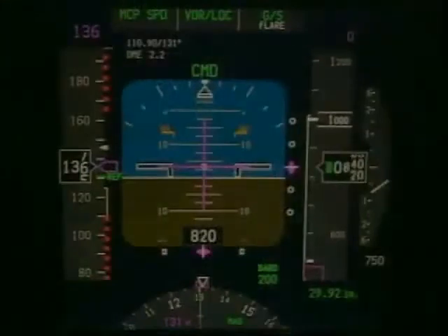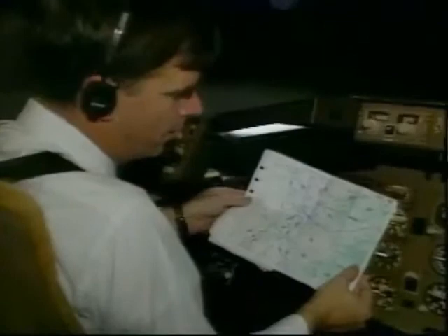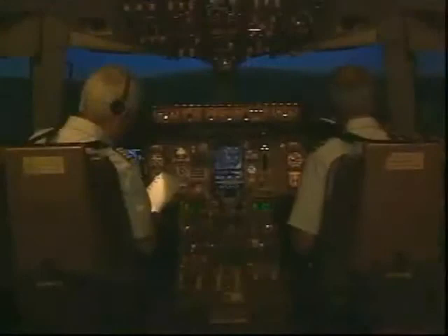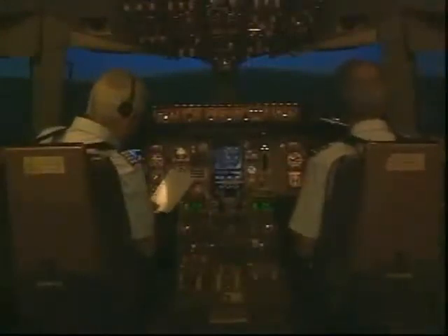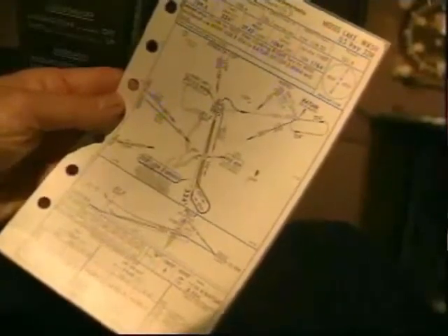Plan on a safe arrival before an on-time arrival. Know where you are vertically. You are responsible. Be aware and discuss minimum safe altitude, area terrain, terrain clearance, and altitude corrections if abnormally low temperature is a factor. In short, use the approach briefing to thoroughly discuss the approach and the use of all available resources.